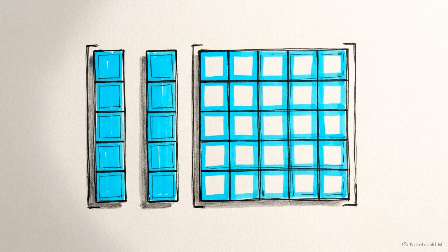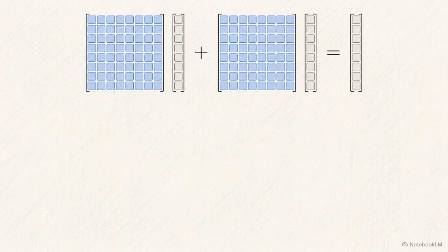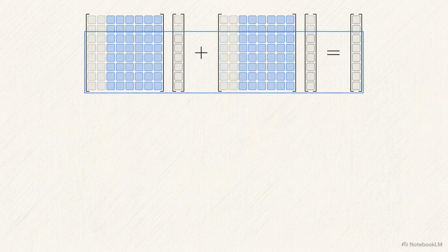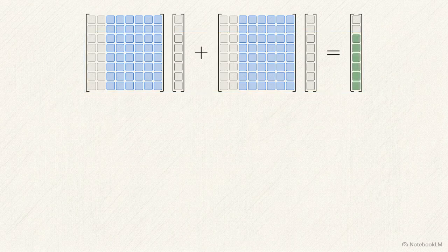Enforcing zero displacement constraints surgically removes specific columns from the system's influence, stripping away the singular nature of the global matrix entirely. With those columns deactivated, we shift our analytical focus to the remaining active rows. Rows 3 through 8 represent the free nodes of the beam, nodes 2 and 3. In these specific rows, the external applied forces are strictly known quantities. This leaves structural displacements as the only unknowns.